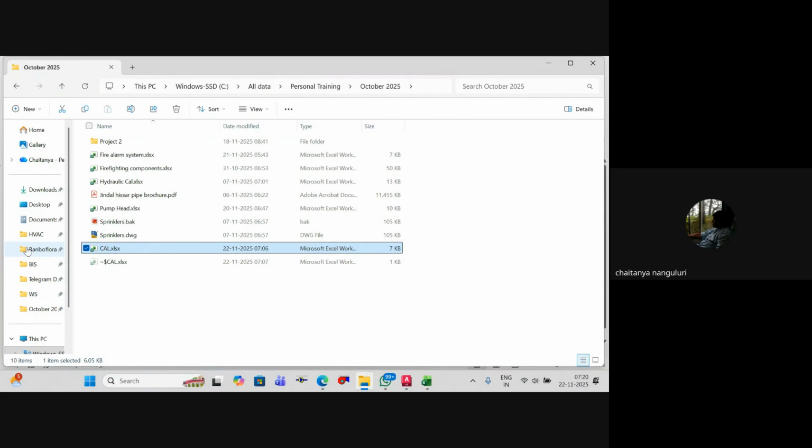Either I'll try to cover it today or, if not, we'll work on it in the next lecture. There is something called VESDA, very early smoke detection aspirator, where you have a tube with small pinholes on it, with some sampling points. Through the sampling points, it will suck the air. So you have that particular application. Understood? Okay. So now we're going to continue with the sprinkler system anyway.